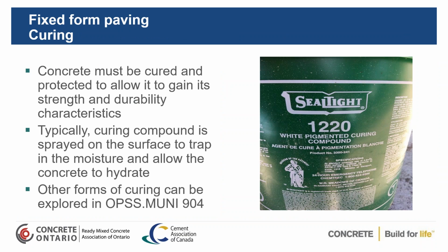Curing is extremely important in concrete. If you don't cure the concrete, you're not going to gain the strength that you were supposed to in the design. You'll dry out the surface, and the concrete's going to be weaker at the surface, so it's actually going to lead to scaling of the surface of the concrete. So you want to make sure you use your curing compound appropriately.